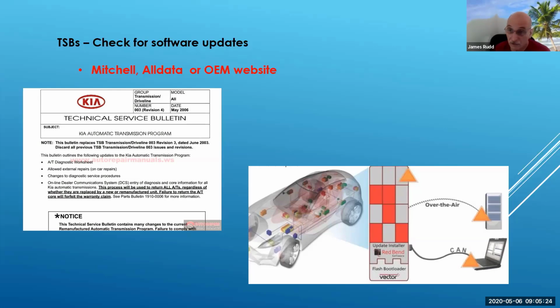Well, I pulled codes on it, and I found that it had a small evap leak. Now, an evap is part of the emissions package on all cars. It's to control the evaporative emissions from going out into the atmosphere, and they pretty much self-contain themselves. Well, I pulled a small evap leak, and one of the practices is to put the tank under slight pressure with smoke.